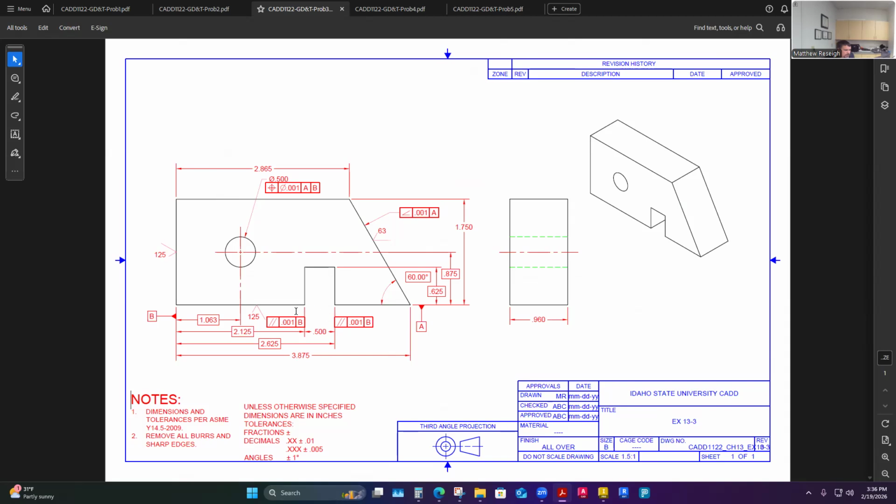So that's something that's a little more complicated. Remember, our surface has a break in it. So are we calling this datum A or are we calling the entire thing? And I may have to call that out. So I'll look that up. That could be an add-on or part two if I do a little meditation and homework on this thing. But for right now, I'll keep it this, which implies this surface is our datum A. And so all dimensions are really based off datum A that might be in this height direction.